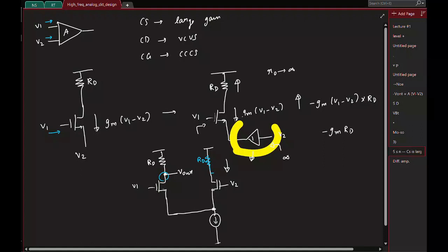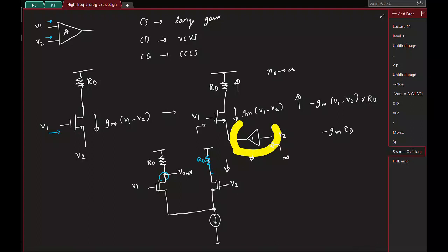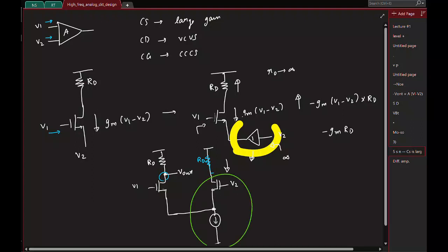if you have an ideal voltage buffer, but we know for a fact that this guy is not an ideal buffer, right? Why is it not an ideal buffer? What is the non-ideality in this? The output resistance is not 0. What is the output resistance for this guy? Common drain. What is this? 1 by Gm. So this is obviously not an ideal buffer.